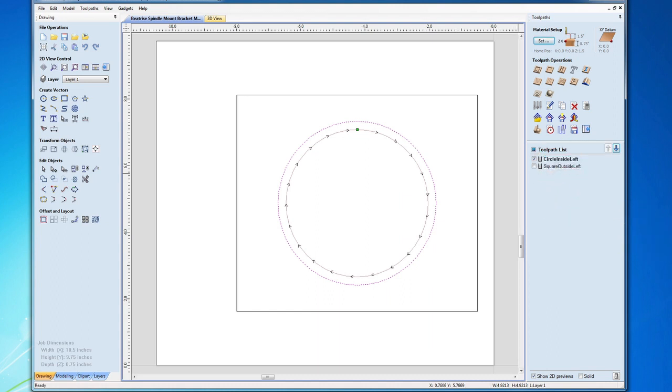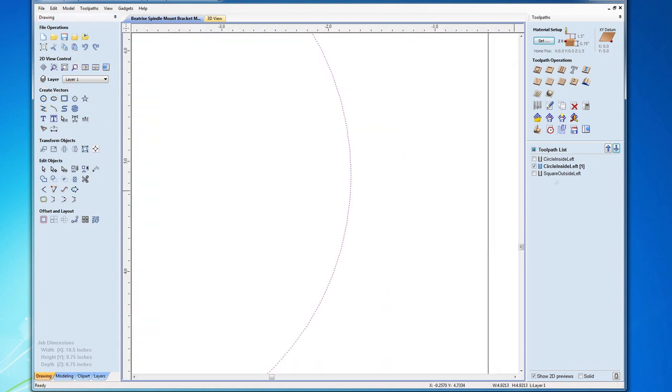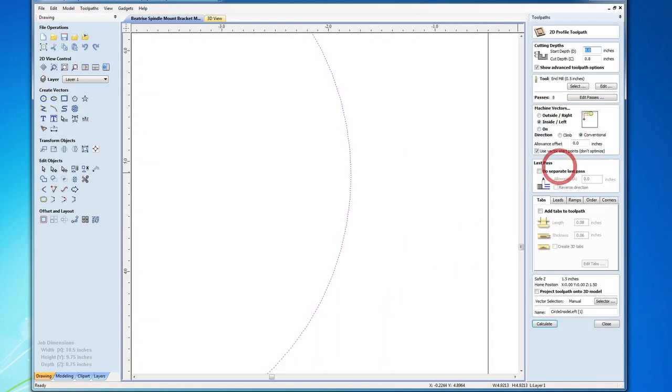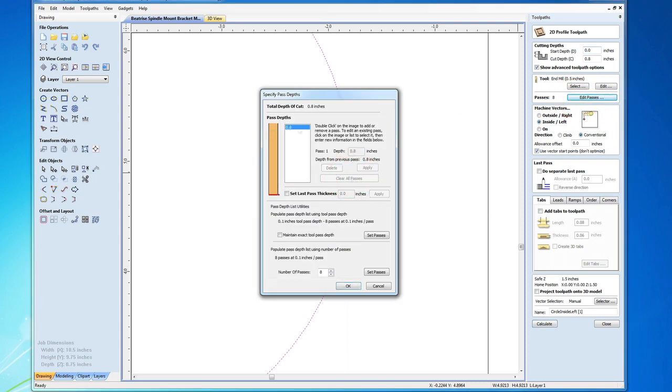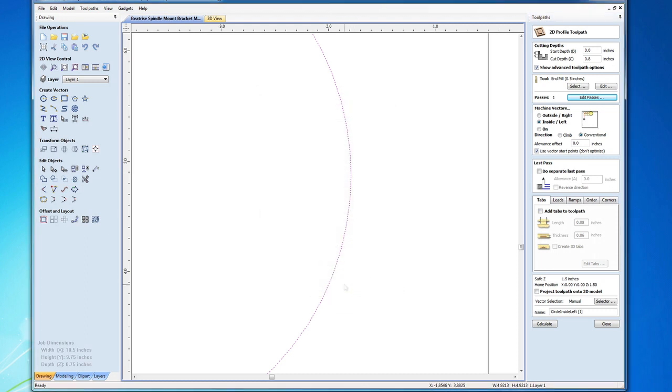is this. I take my toolpath and I duplicate it. So I've got a copy of that toolpath, and I'm going to uncheck the old one from the visibility profile so you no longer see it. And I'm going to zoom in so we can see what happens here. I'm going to double click to edit this toolpath. I'm going to edit the number of passes, make it just one pass now, because I want to create a toolpath to shave those edges that I've got.